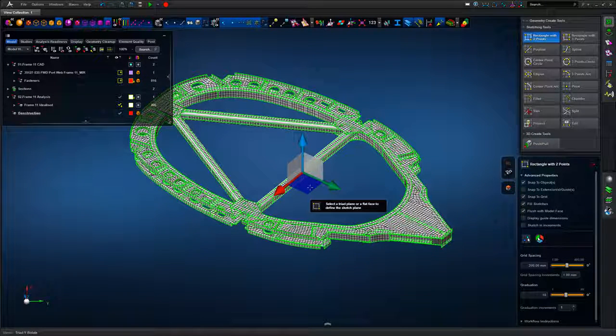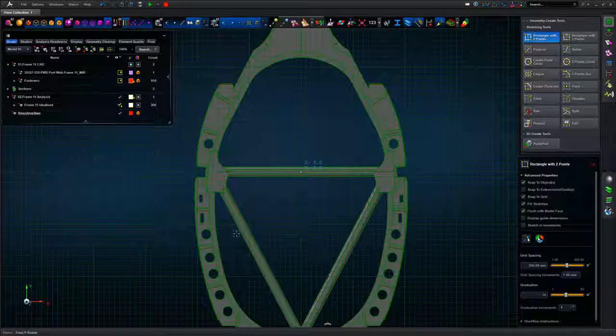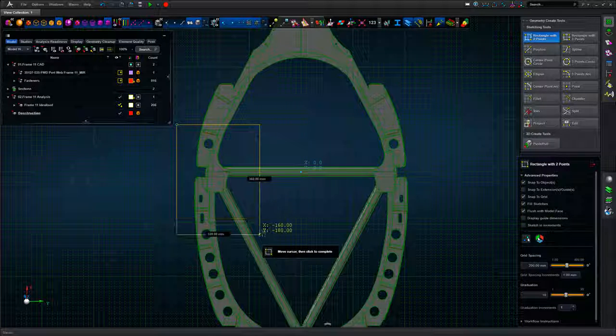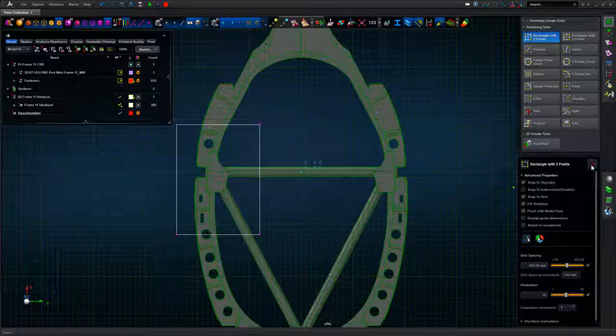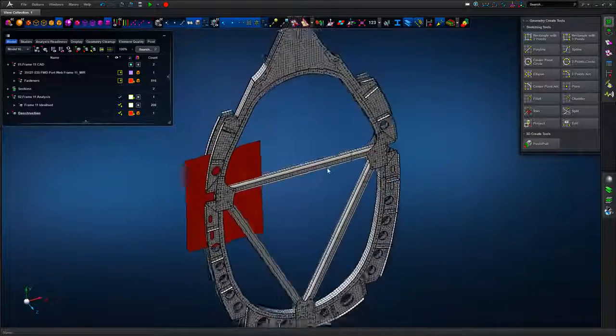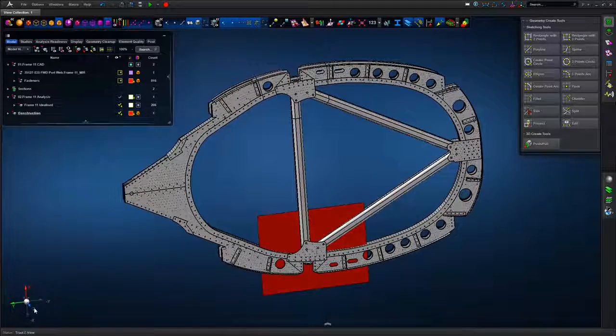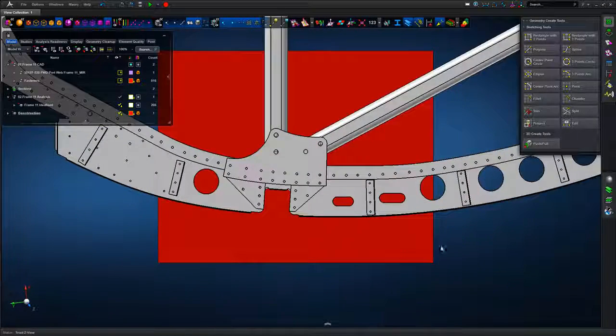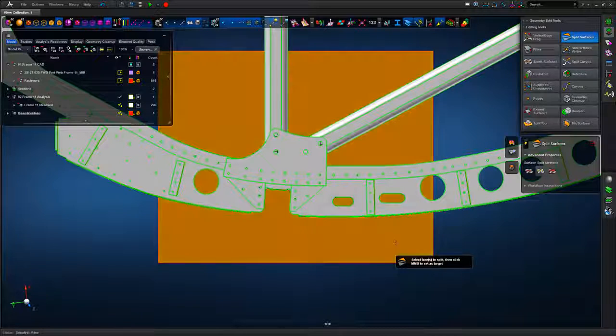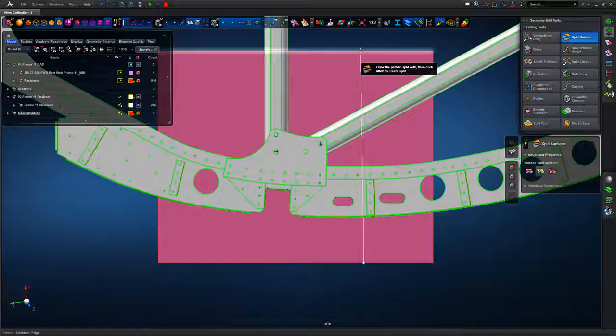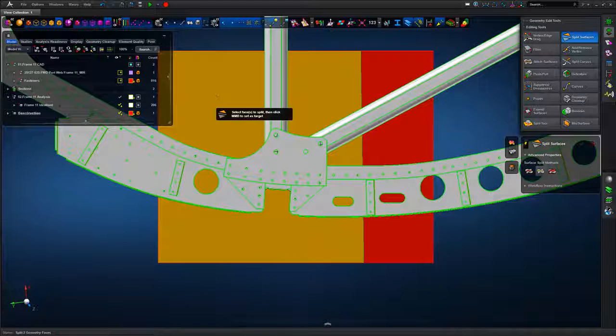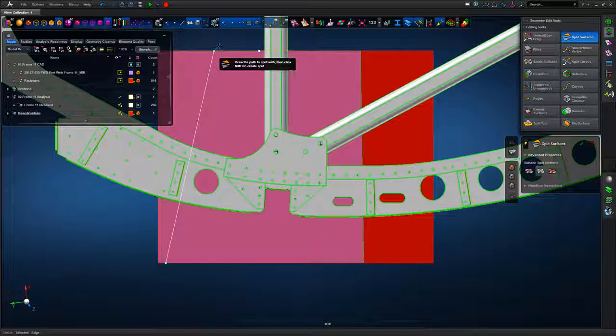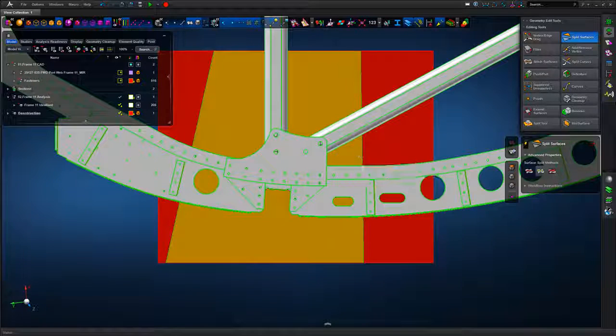So first of all, we're going to use some of the sketching tools to just cut or chop, for want of a better term, a portion of the original assembly definition out to create a region of interest assembly and control that using whichever means we need to within Apex. So first of all, sketching a surface normal to the cut. So once we've got that, we're basically splitting this surface in a manner which will allow us to cut the overall grey assembly shown on screen now. So if you just bear with me, the cuts will make sense in a moment.